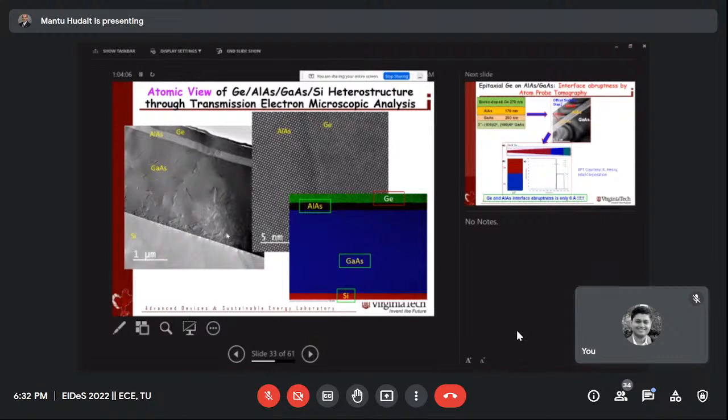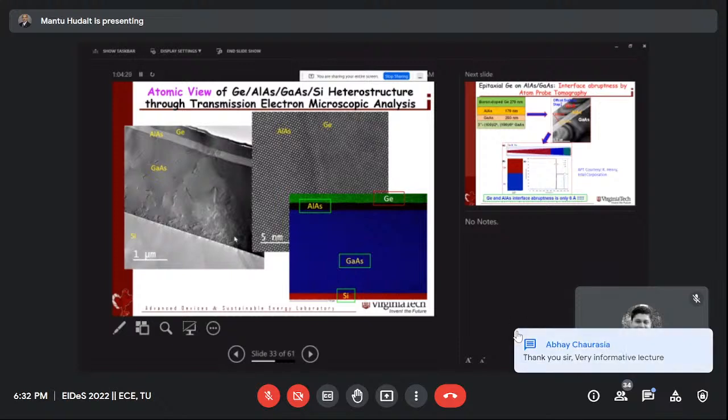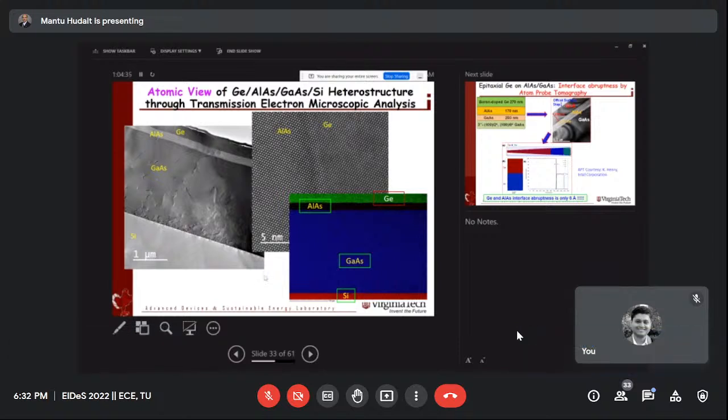The critical part is fabrication. The problem for us is the device, the last part, where we all get stuck. Because we don't have e-beam lithography, we all get stuck. That is basically our problem. We understand the material, the interface, the defect engineering, the X-ray of the material and the interface. Then circuit simulation, the students are doing it. But how about a 20 nanometer transistor? We cannot do it here.